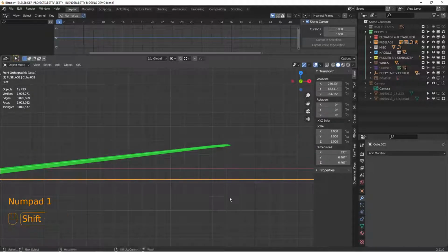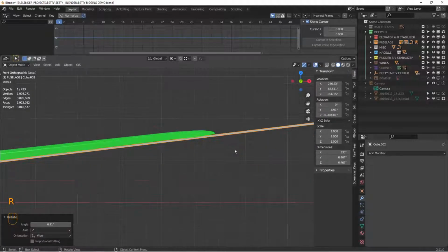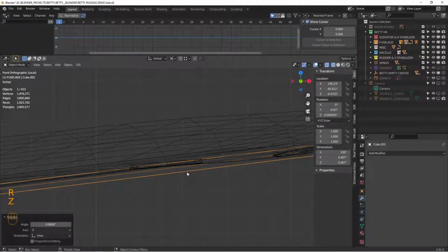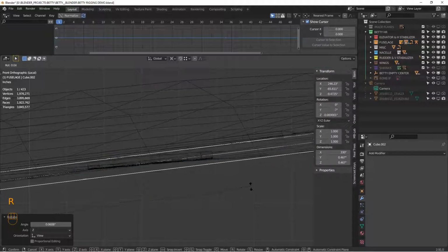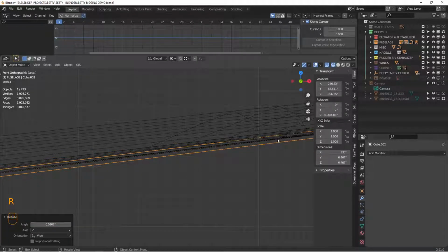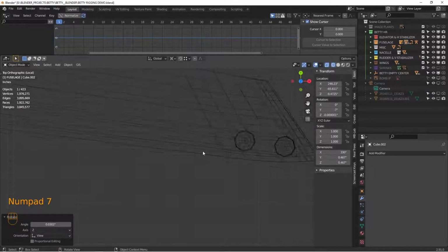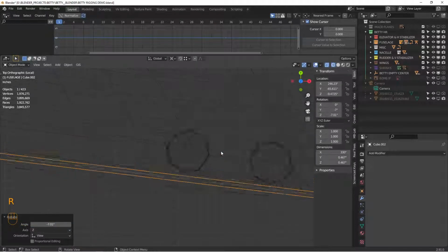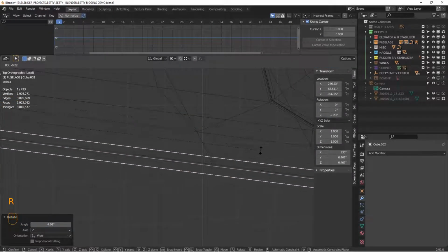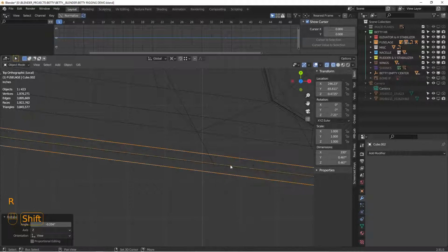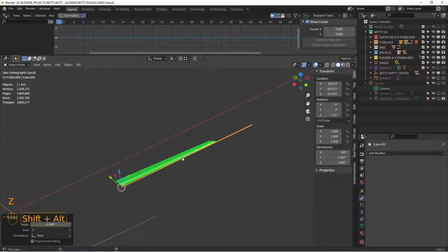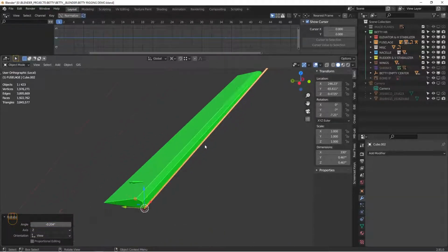We're going to do the same trick we did before where we rotate this piece, and I'm going to use this center line to get me roughly where I need to be. I can see this orange line running along the front of the aileron, and we're going to rotate it again this way and do the same thing here. So we got a line parallel to that. All right, and that's going to define our new axis of rotation.